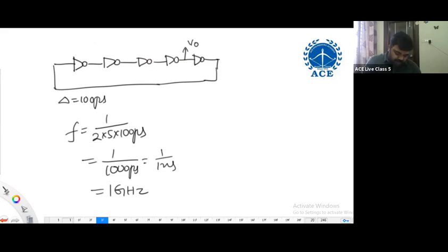That's what I've been explaining, Nitesh Kumar Yadav. Yes, it is circular arrangements. Every inverter is seeing back how many inverters? 5 inverters. Every inverter is seeing that. So no need to think it is becoming bistable at the 4th inverter output.